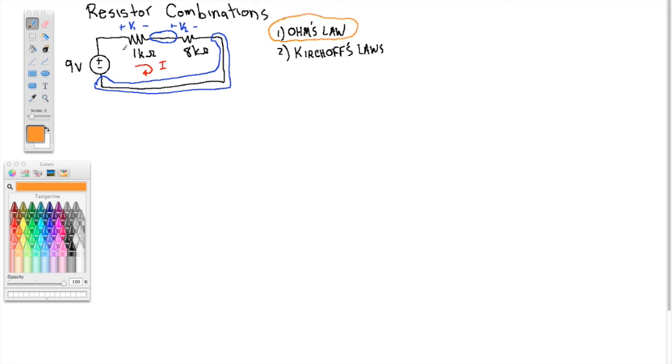and that's because it's actually very seldom that we know the current through or the voltage across. And to use V equals IR, you need to know either the current through the resistor or the voltage across. And I want to point out in particular, this is a pitfall that I see from students. You look at this 1 kilo ohm resistor, and yeah, it's connected to a 9-volt source here.